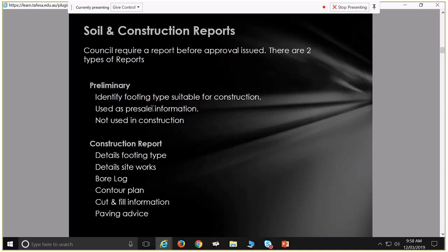Yeah, exactly. Yeah, no, that's an excellent description. So it's a slotted pipe, flexible black pipe with lots of these slots in it. I'm fairly sure probably everybody would have seen some of it lying around at some point in time. That enables moisture that's in the soil or water that's in the soil to seep into that pipe and then run away. So it's put on an angle, and as you mentioned, it goes behind retaining walls.